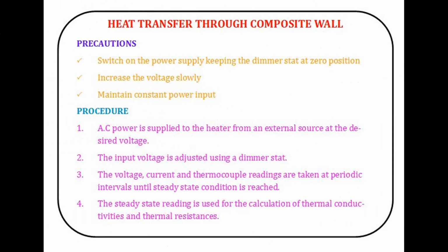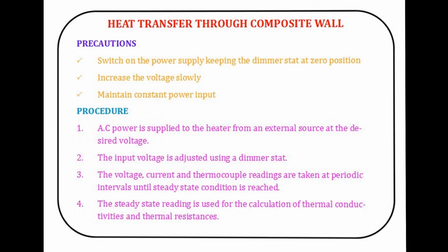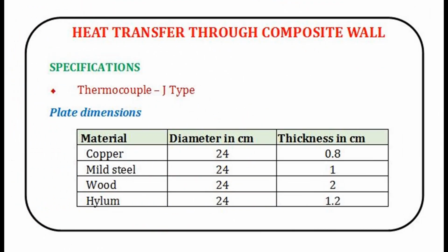As a procedure, we need to start the AC power, which is the input heat energy to the heater, using a dimmer stat. So we will be measuring the temperature using thermocouples, and this is the plate dimensions. The diameters are the same, but the thicknesses are varying.